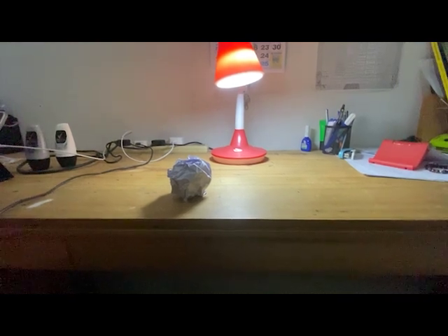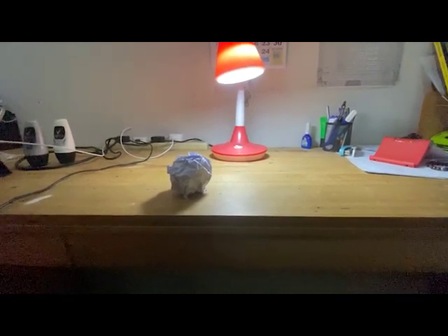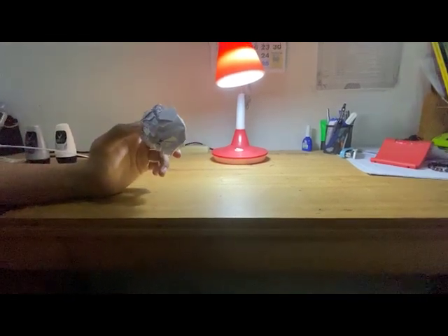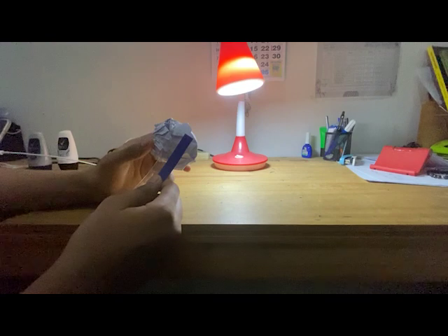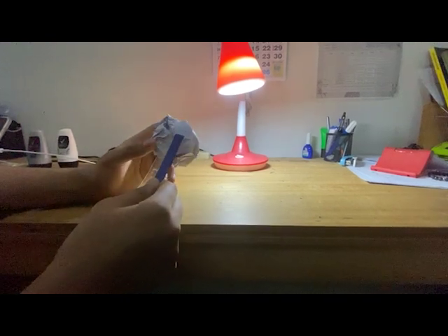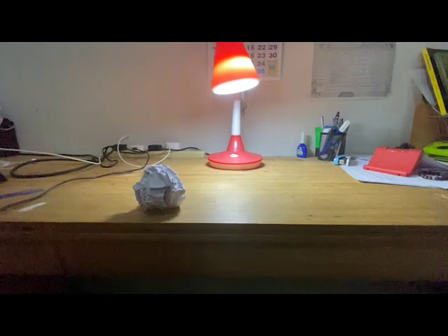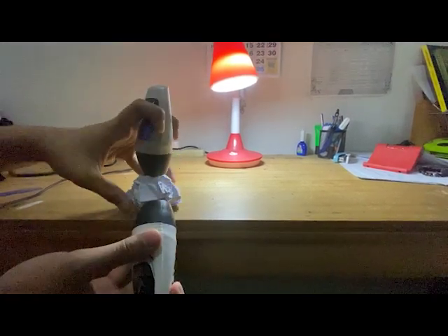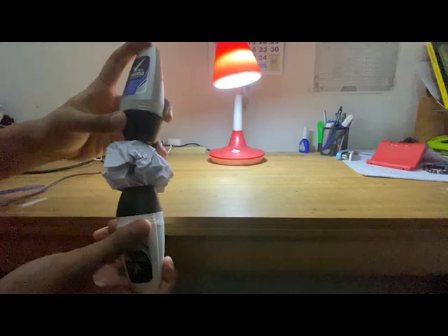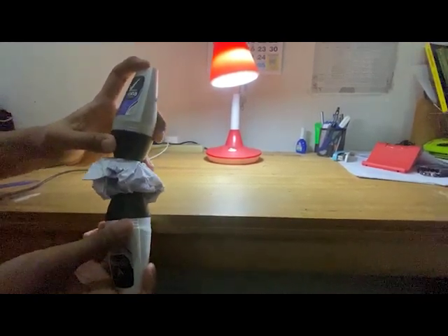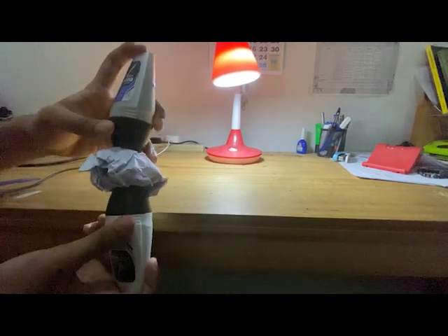The procedure for the point load test is, first, we take the irregular rock sample and measure the dimensions of the rock sample. Then we place the sample between the pointed loading platens. Then we set the hydraulic reading, and after that we compress the rock sample until it breaks. Then we record the maximum pressure that the rock can withstand.